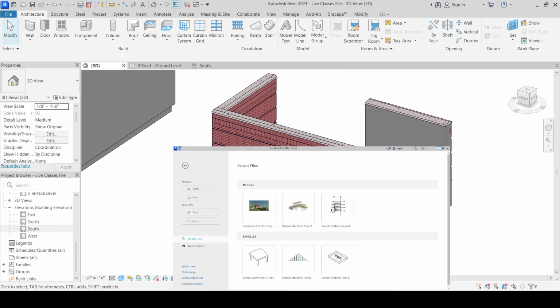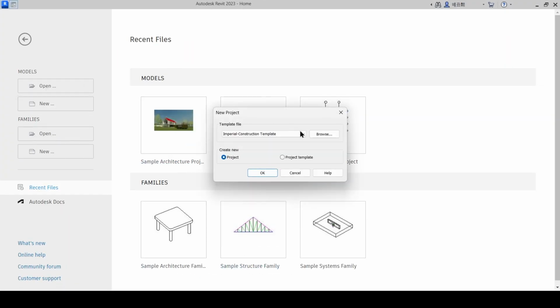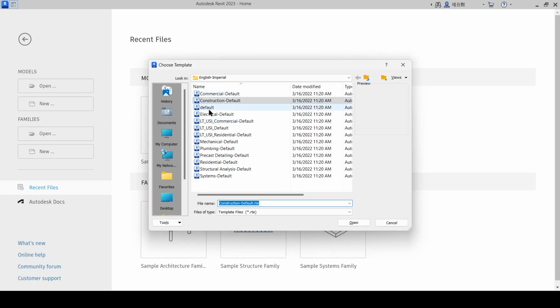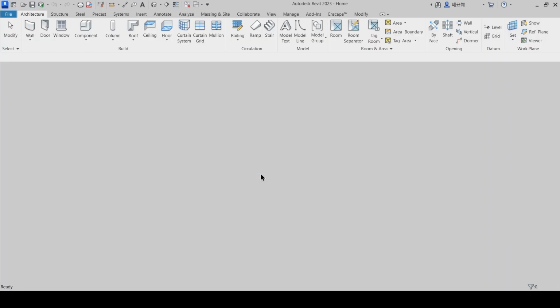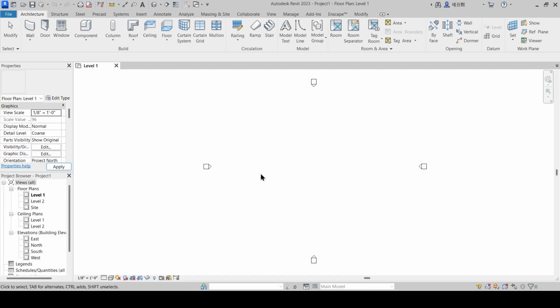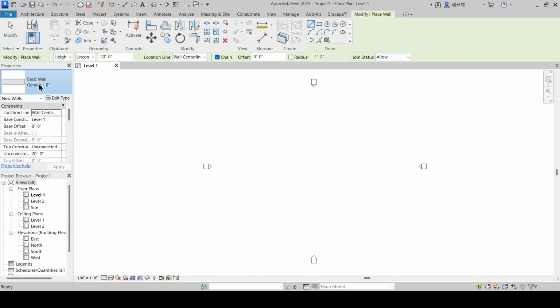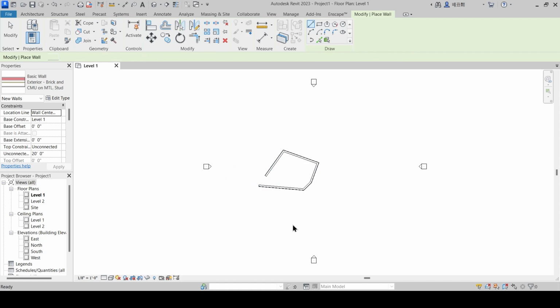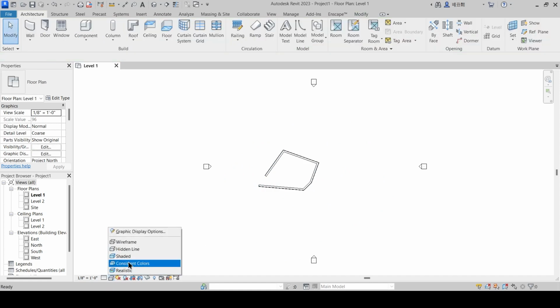Okay, in earlier versions of Revit, if I just take it to 2013, the versions of Revit less than 2024, this was one major change, one major difference. So that's why I thought that let me just show you, because all of you will not be working on 2024. So if I just select this wall, fine. Then if you just click this, then you have all these categories, consistent color, and then straight away realistic. You don't have the option of texture.